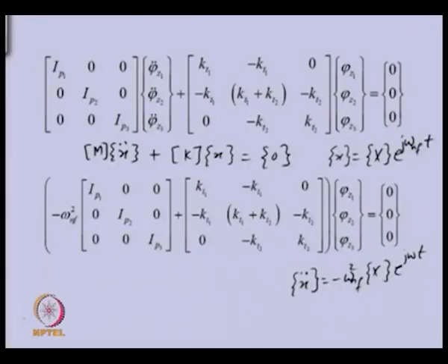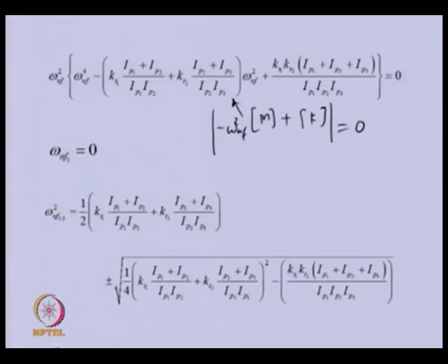Now, when we have a multi degree of freedom system, we need to obtain the relative twist or relative angular displacement of the disks, that means the mode shape. So now we will see how we can obtain the mode shape from our equations of motion. For that, we will take this particular equation. In this equation, we can expand any two of the equations, like the first equation and the second equation, and in the subsequent slide we have that.